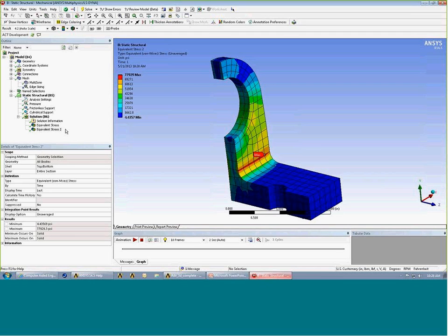So even though our mesh here was reasonable, according to our element quality measures, it's not reasonable for extracting stress values. We have a mesh that was not fine enough to get good stress values, even though the quality was acceptable. So we would need to go in and, based on these error measures, refine our mesh and do some effort in there to get more elements around the fillet, and we would go and create a